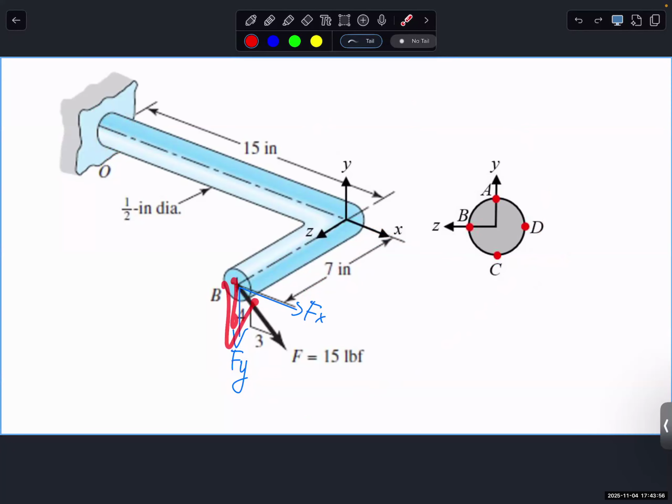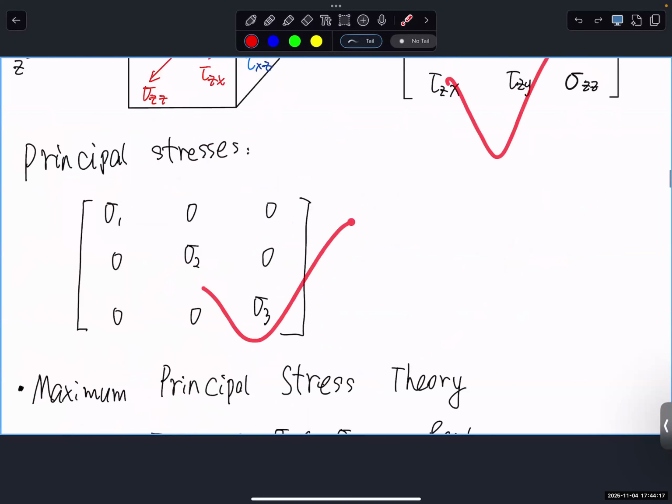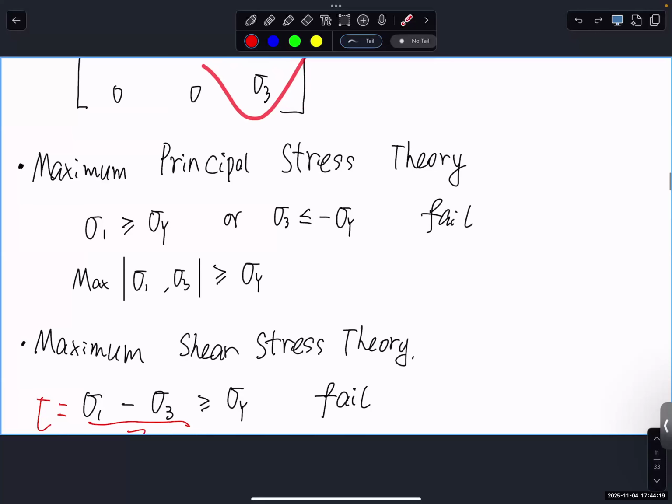It also becomes a transverse shear, so it generates a shear stress caused by transverse shear. So in the end, it's not really one component. It is multiple stress components caused by different failure modes. We calculate all those stress components, calculate the principal stress, and use different failure theories to decide if everything is okay. This is the basic procedure, all in mechanics of materials.